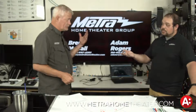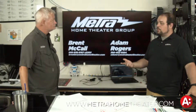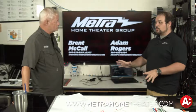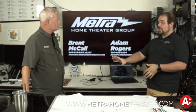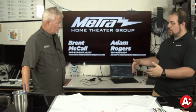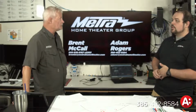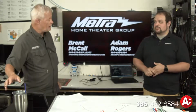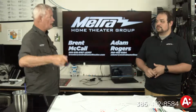Yes, and actually you can see those. I mean, they're out there. They're the power over HDBaseT stuff. It's mostly in the Infocomm world, the commercial world, but they're definitely out there. I do know HDBaseT is really pushing for it to become more of a standard inside the home. Which is why you want to go to Cat 6A. Yes. For nothing else, extra copper matters. Yes, it does. Loss is definitely different between Cat 6A and Cat 5e.